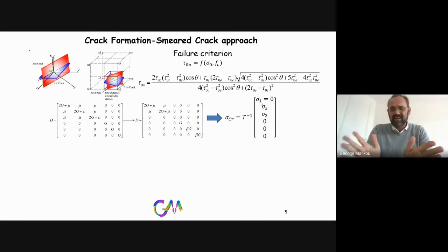And then that crack remains open until it closes. So if in another step you recalculate and find that the crack direction is changing, you are not rotating the crack, because in reality, a crack opening will not close and then reopen a bit lower or higher, unless you have a second crack opening. So you will have this case here, as you can see.